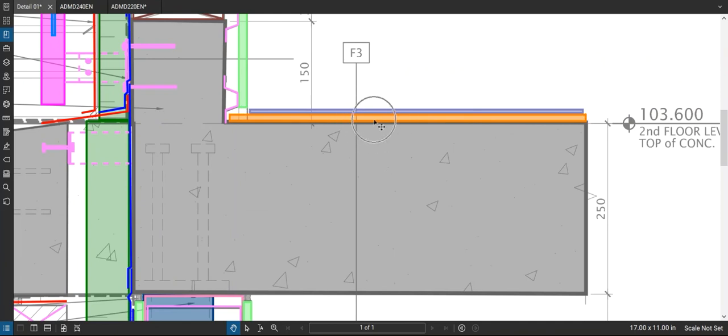I would say would be the acoustic mat, and then the floor finish, especially if you're going to have a hard floor finish. So the concrete structure itself, a 250 slab of concrete, you might think, well, that's got to be good at controlling acoustics, and it is from an STC standpoint. So from an airborne noise standpoint, it's pretty good. But if you're walking on or drop something on a hard surface above, that sound will travel through no problem. So adding more layers up here starts to help improve the IIC, which is